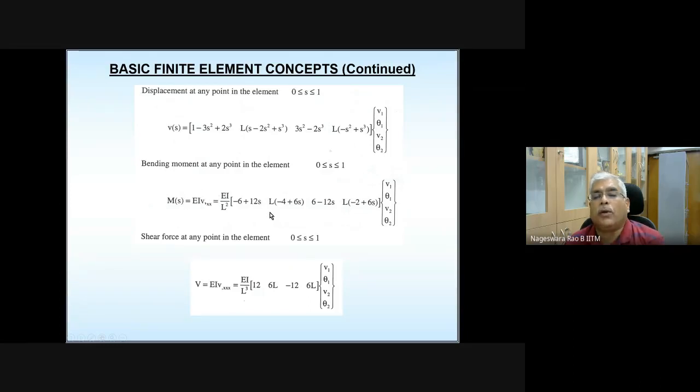So please take a note of this bending moment. And if you take one more derivative of this curvature and multiply with the EI, you are going to get shear force. So please take a note of all these equations. Then we will see an example.